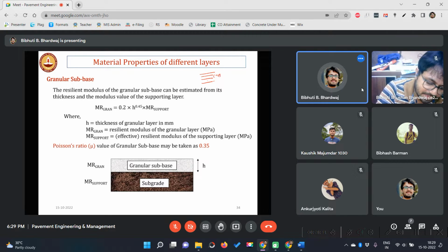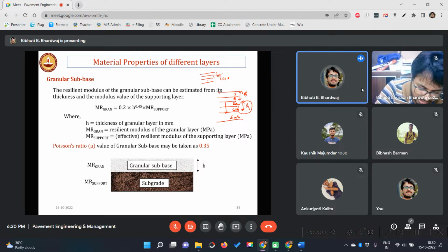Sometimes it may be cement treated base, cement treated subbase, granular subbase, granular base. Now if I divide these layers accurately into its components, this is subgrade, this is subbase, this is base. These two are generally considered the same layer, granular layer, even for design. And this was a surface course and binder course. This was a bituminous mix. In the granular layer there are 2 layers, one is subbase, one is base.